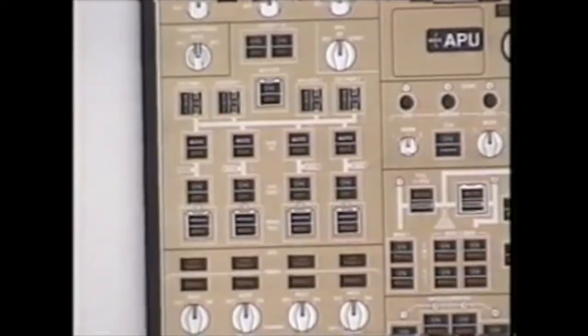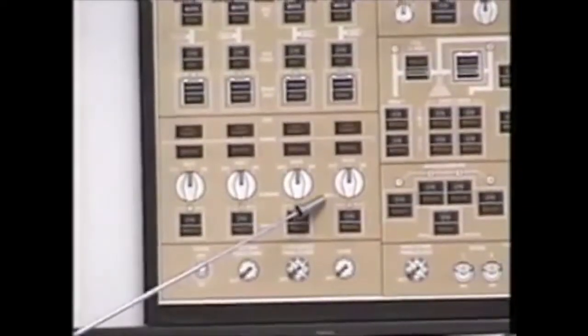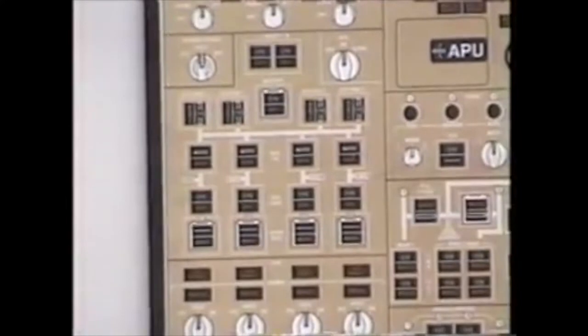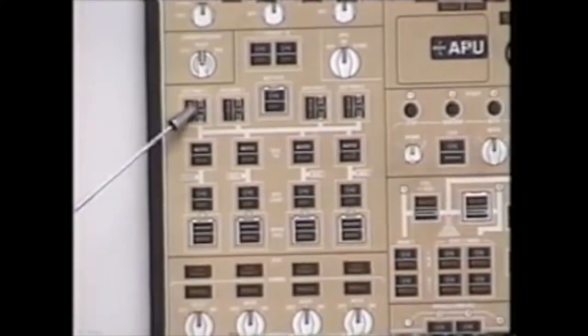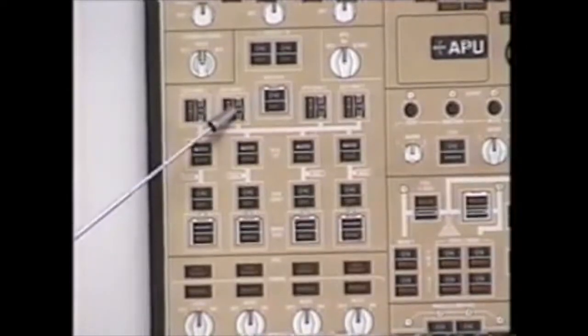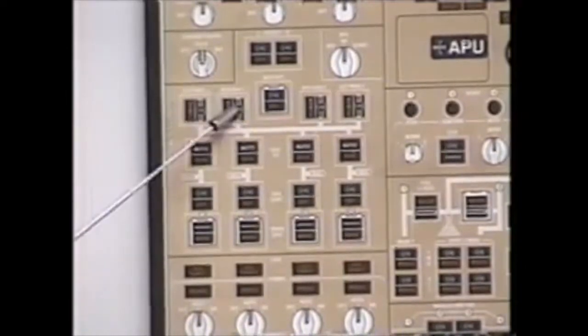The ground handling bus provides power to items such as the cargo loading, to include the doors, the lights, the rollers, fueling, except for your stabilizer, and the aux hydraulic pump in System 4. The primary power source to that ground handling bus is external power number 1, backed up by APU generator number 1. Powering the ground handling bus requires the avail light or the on light in either of these 2 switches.